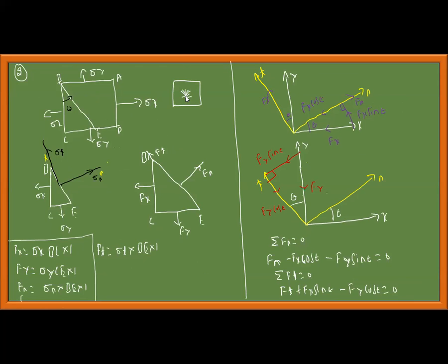For any plane, the state of stress changes, but the principal stresses sigma 1, sigma 2, sigma 3 will remain the same. It depends upon what is given for this plane, sigma x and sigma y. We need to calculate the principal stress, because principal stress is an invariant. It will not change if you change the coordinate system.